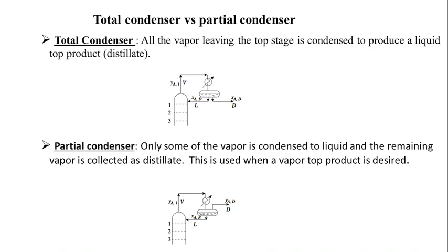On trays, you have vapor disperser units. What are these? These are the valves, the bubble caps, or it could be the seals. In order that there is vapor-liquid contact on the tray, these have to remain submerged. The amount of submergence will depend on the level of liquid on the tray, and this liquid has to overflow over the weir and go to the downcomer and fall to the next tray.